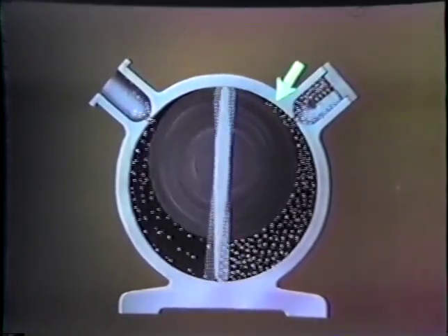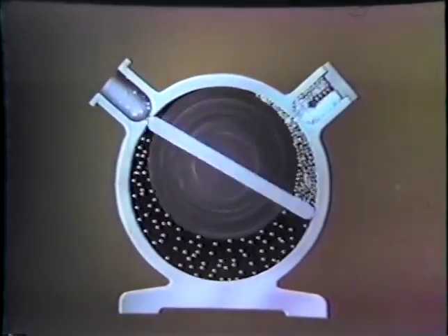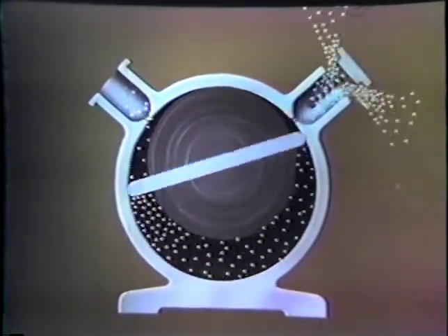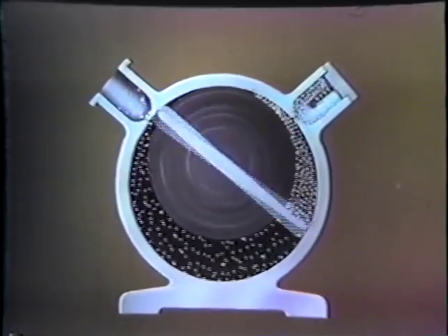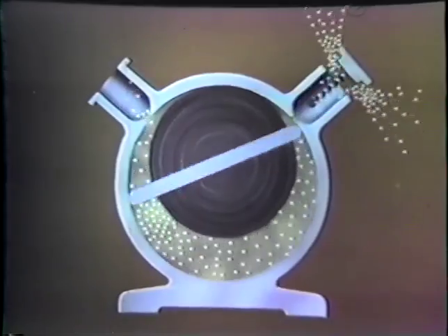The leakage between the outlet valve at atmospheric pressure and the inlet space at vacuum limits the pressures that can be reached by these pumps. Another limitation is the vapor pressure of the oil used to seal the flow of air between the various parts.